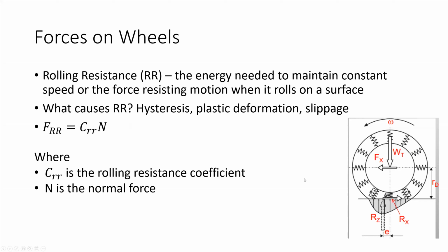And then I think the last force is acceleration force. This is the force necessary to accelerate the vehicle from a complete stop to maximum speed in a desired time. We know that force is equal to ma, and you can break that down: mass turns into weight over gravity, and your acceleration turns into velocity over time.